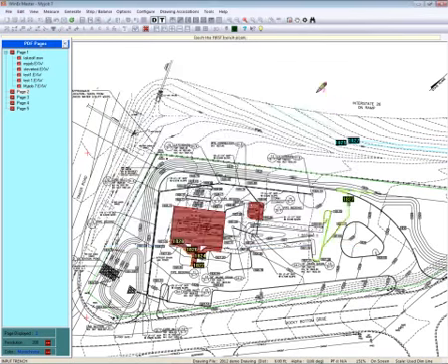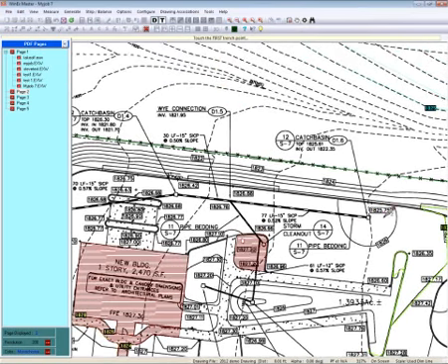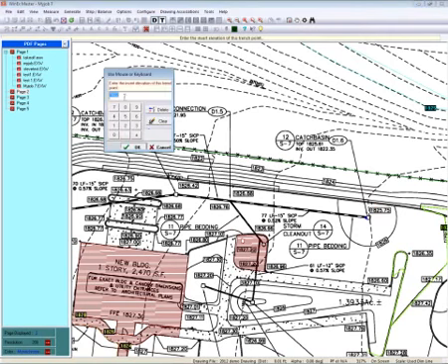And then it's just a question of clicking on where that trench is, and let's come in here. And if I had put my manhole cover in, by the way, we use our count feature to put manhole covers in, and you can use different symbols for it. But here I'm going to come out at, let's see, I chose by the invert level, so I'm going to go in, I'm going to go up by that. Let's say 1822.35.